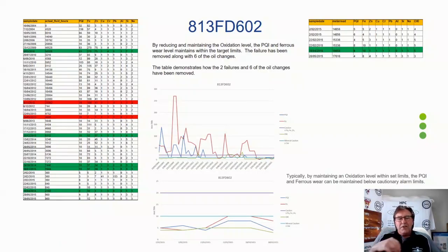So what we needed to do was understand what was going on with our lubricants, right? So we had our dirt signatures, and again, we maintained a dirt signature below, but what we were finding in this was we were having a high oxidation level, so we looked at trialing different types of lubricants, like increasing in viscosity due to the oxidation or the thermal degradation failure. We looked at going with synthetics.